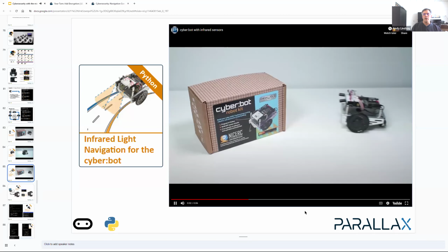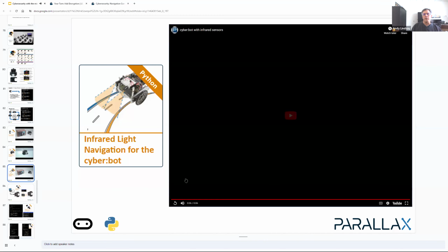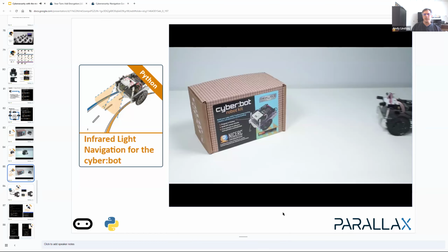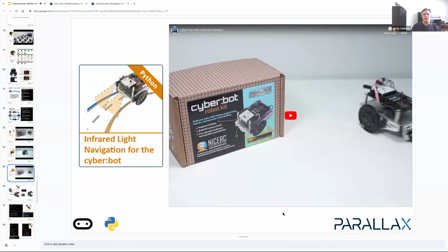And so here, those little black tubes sticking out of the Cyberbot robot are little infrared flashlights that are flickering at a certain frequency that the detectors that are also built on that breadboard are capable of detecting, the reflected infrared as it bounced off the box and then off the wall in the back.